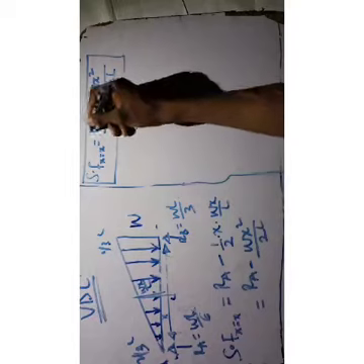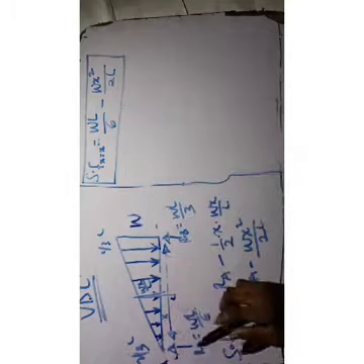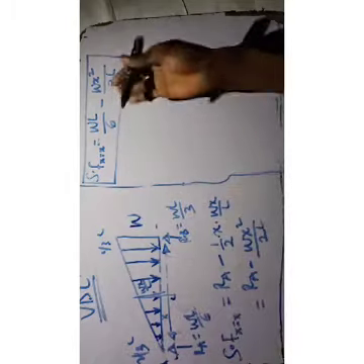I said combined load. So now you can apply the shear force at any point. Okay, so you want to find the bending moment as well. Don't forget, you want to find the shear force at this point. What is it? WL over 3, and at this point it is WL over 6. You can apply this, you see, and you have 0 as well.